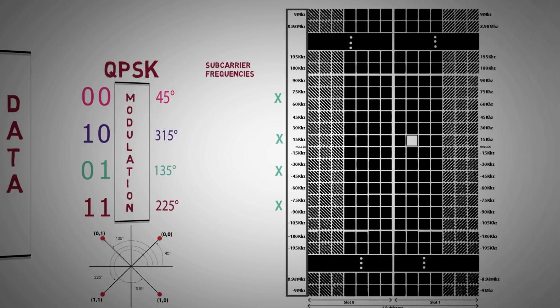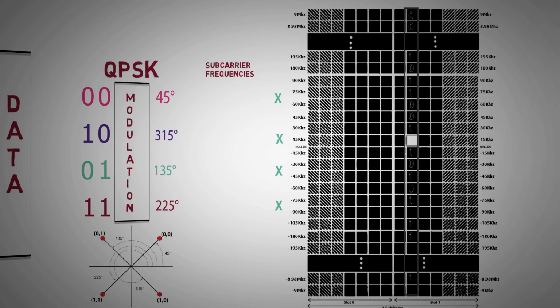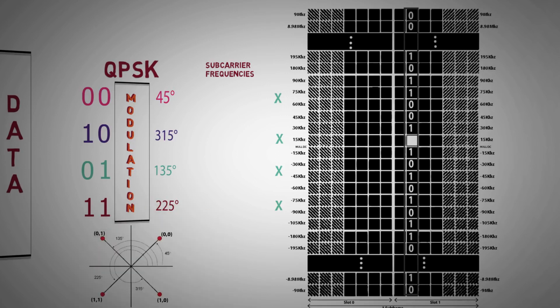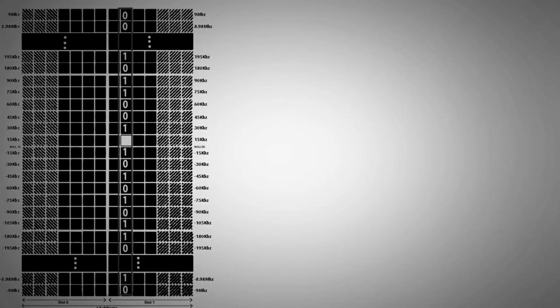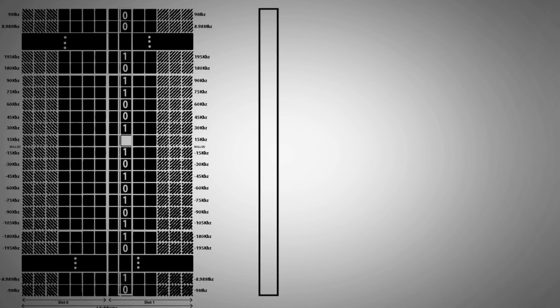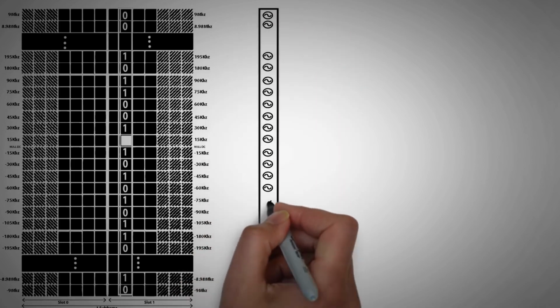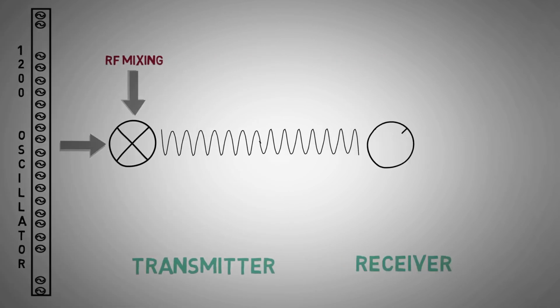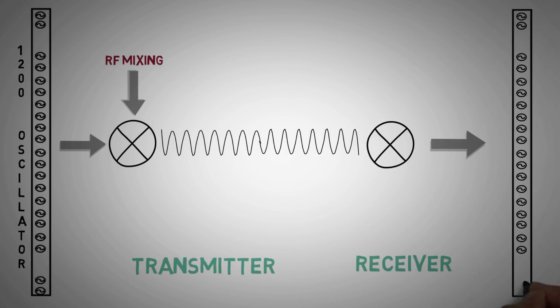Thus, in a 20 MHz channel, all the 1200 resource elements carrying 1200 symbols over 1200 subcarriers are modulated with the appropriate modulation scheme. Since the data is modulated over 1200 subcarriers, a transmitter will require 1200 oscillators for its generation, and another 1200 will be required by the receiver for proper demodulation.